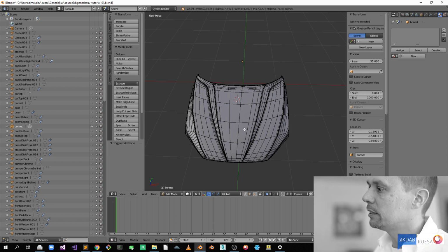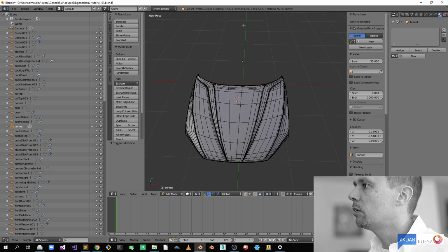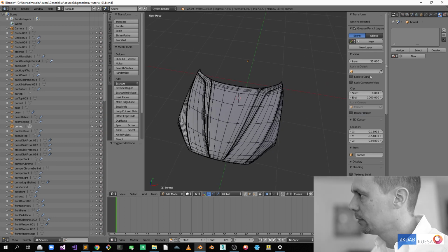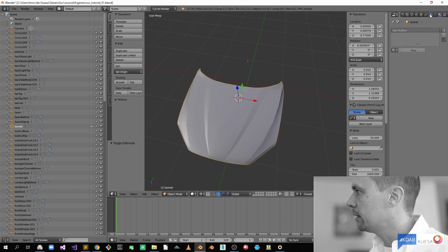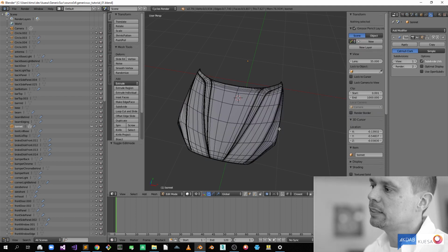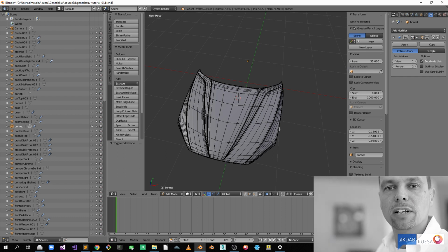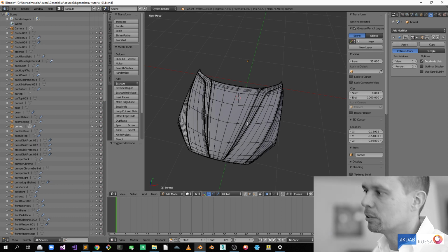So what we are going to do here is increase the overall mesh resolution and later manually reduce it again where we need it. So let's see, we have now around 4K faces. Let's add a subdivision modifier. We are lucky in this case because the mesh is built in a way so we can apply a subdivision modifier, but if you import meshes from somewhere or get an export from a CAD application, for example, that might not be the case. For example, if there is an irregular triangulated mesh, but in this case it works out right out of the box.